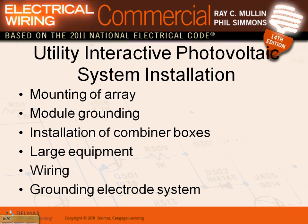Modular grounding, installing of combiner box, large equipment, wiring, grounding electrodes. All these are concepts that, when you install them, you have to pay a lot of attention to mounting the arrays to get the most efficient part of the sun, obviously. Grounding the modules most likely would be a number 6 CU copper conductor.